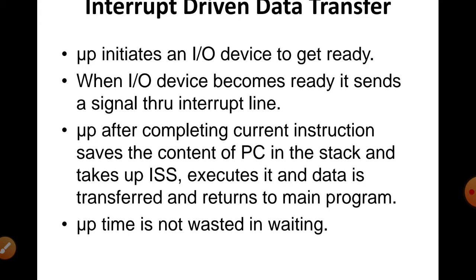When I am talking about the call location, it is the location where a certain subprogram has been written, and the content of that program is such that the device which has interrupted the processor will be able to transfer the data. So actually the content of the subprogram or the subroutine is to transfer the actual data. Besides that, 3 are vectored, and every vectored interrupt has its specified location to which the call transfer is to take place.